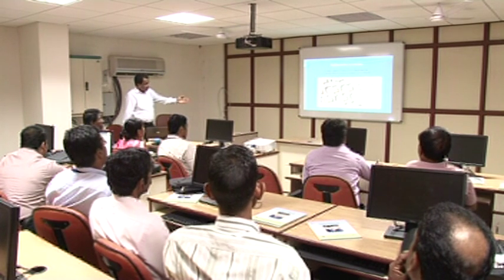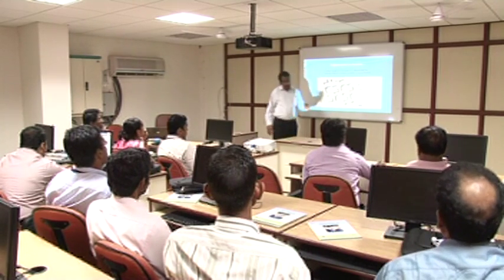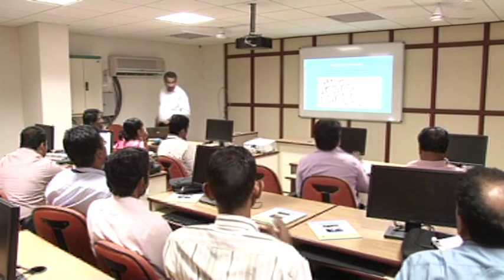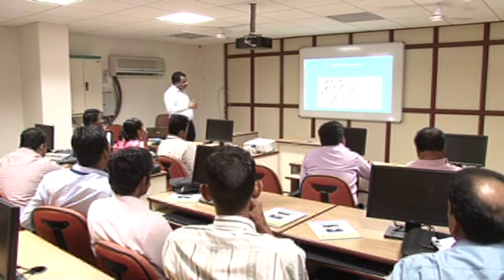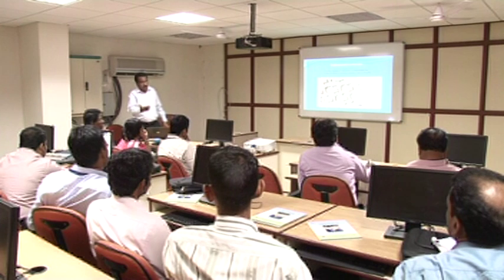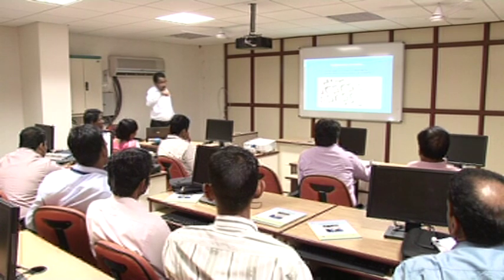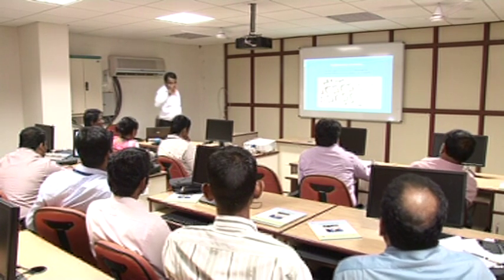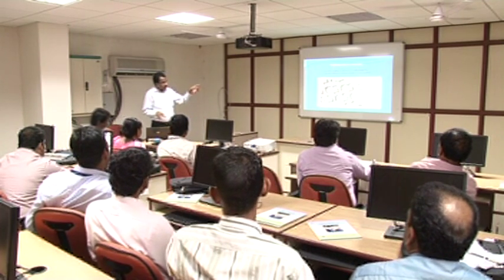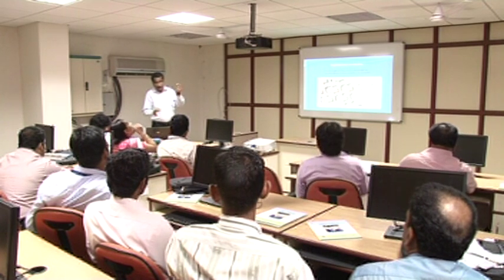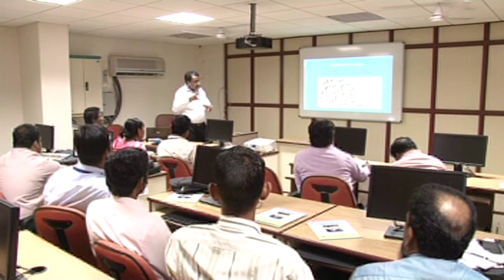Now the radiometric resolution. So it is the capability of the sensor to differentiate spectral reflection coming from different objects. So that radiometric resolution is based on bit information. That is the binary. You know that it is base 2. So 2 raised to n minus 1. That is the bit information. That means, suppose if a sensing system has 8-bit data, that means it will have levels of 2 raised to 8 minus 1.